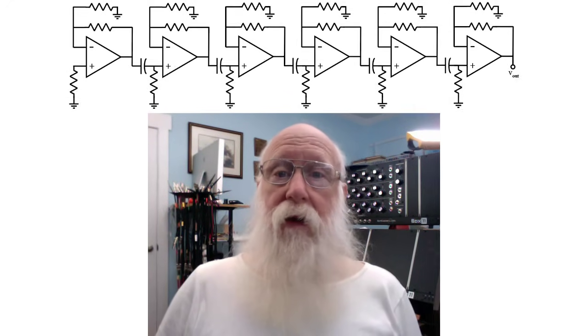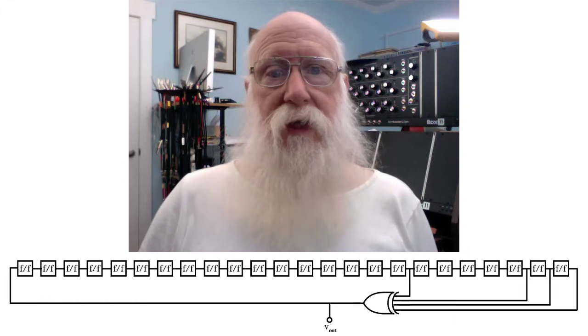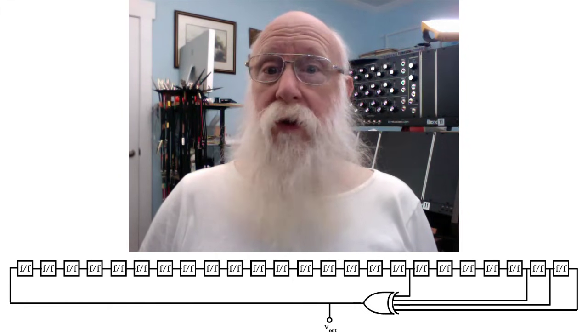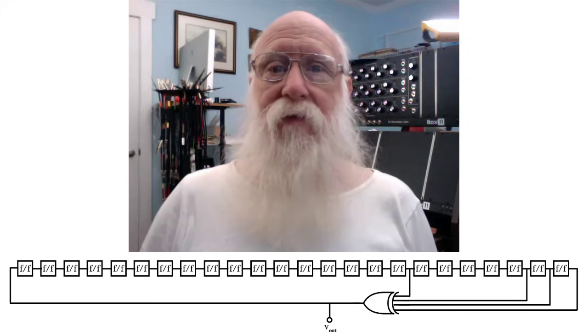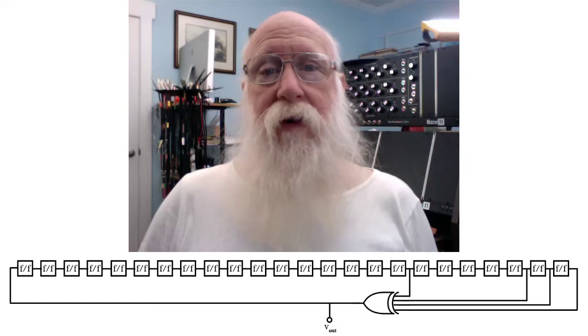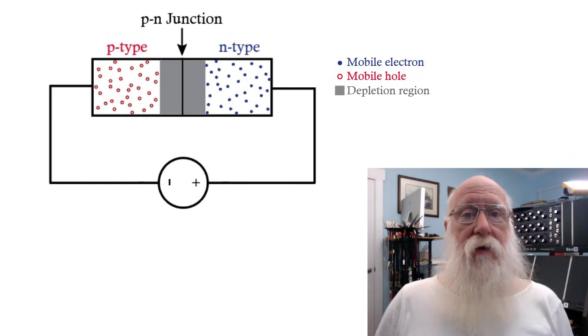themselves generate. If we were doing this digitally, we would probably implement a primitive polynomial using a shift register to generate what is called a maximal length pseudo-random sequence, and this has some advantages, primarily that it actually is repeatable. If you restart the thing from the original state, it will repeat exactly. But that involves digital hardware, and we're doing this with analog stuff. However, the most common means of obtaining a noise signal with a flat distribution with which we can work is to reverse bias a semiconductor junction.